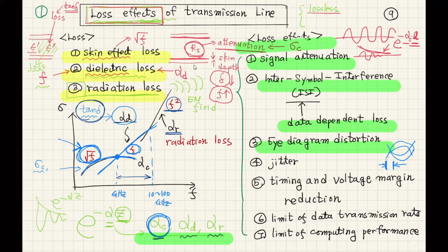So the digital waveform that is crossing at the center line will be different depending on the data because of ISI. That is being called jitter. And jitter is a very big issue, especially at higher data rates. At the end of today's class, I'm going to talk about it more and more.